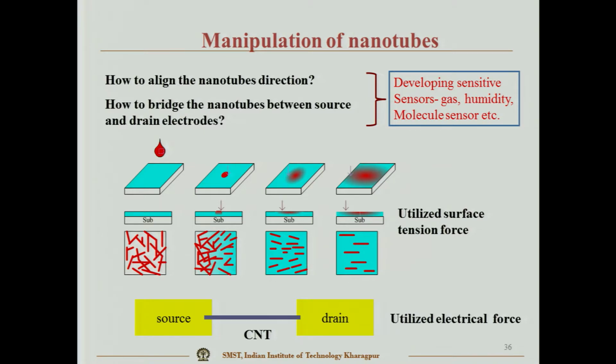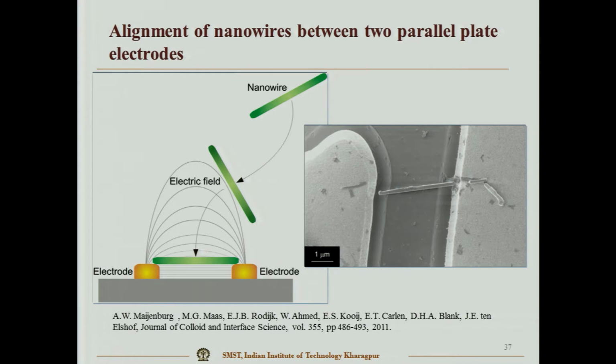And it is useful for sensing gas, humidity, molecules, etc. And this is an AFM photograph, which is not ours; we have taken it from a paper. One nanotube, I have to characterize one nanotube. Characterize means I have to make an electrical characterization of, say, a carbon nanotube or zinc oxide nanotube that we have fabricated, characterized by IV, current-voltage characterization.